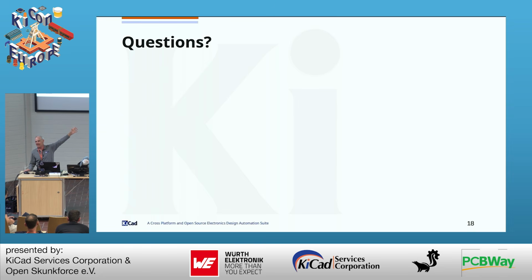Have you ever used that? You've been doing something in the board editor and all of a sudden, like run DRC. If you run DRC and it says synchronize from schematic editor, it opens up the board editor. That's to get the information from the board, because we don't store that information in the board. So you'll be able to maybe select a variant, but it's going to open up the schematic editor and say, hey, pull that variant and then update the board view.